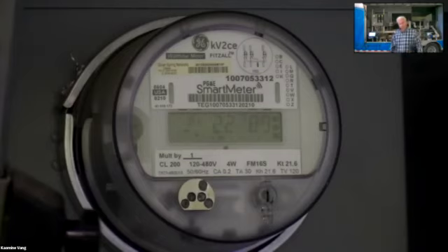Now we're pulling, it's coming up now as it scrolls through on our smart meter. Now we're pulling 2.78 kilowatts. So I slowed the speed from 3,600 RPMs, which on this submersible pump is full speed, to 3,000. I slowed it 20%, but our kilowatts went from 4.65 to 2.78. I slowed the RPMs 20%, but I'm saving about 40% plus on the energy coming into the pumping plant right now. That's why VFDs can save money, because of those affinity laws. And those are kicking in. And I'm still getting the 100 gallons per minute I need on our pump.